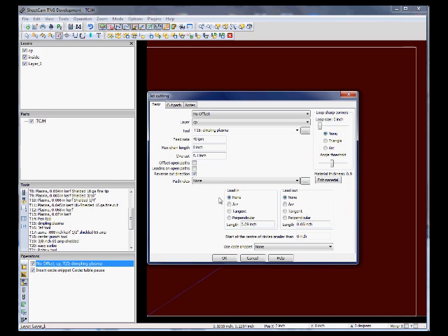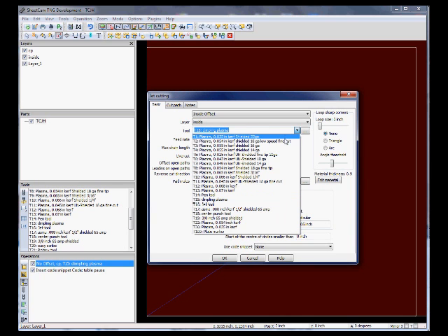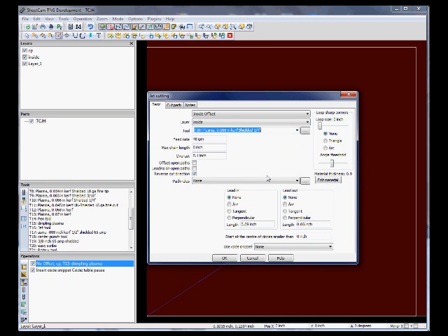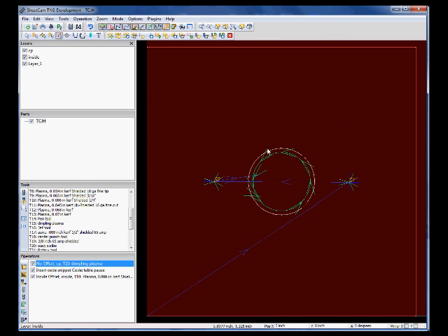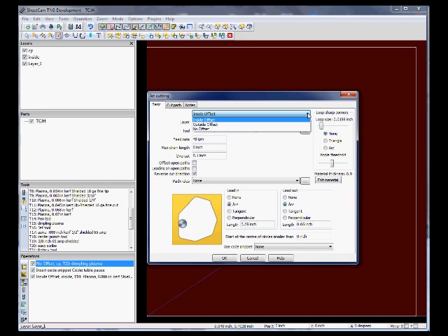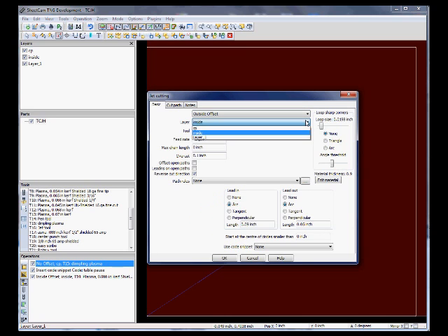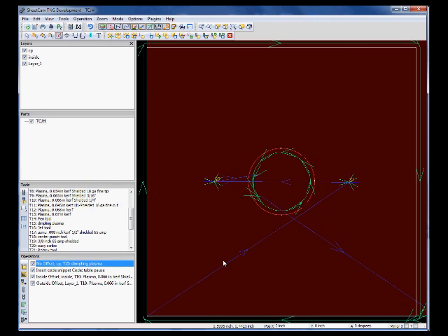and then the next thing I come in here, I'll do the inside offset, and I'll say do the inside and change it to whatever tool you're going to use. Let's say I'm going to use a 1/4 inch. So all the settings are there. You can have lead in if you want, and lead out if you want. So you go ahead and click that, and you see it is set up here to cut the inside, and then the other part is the outside, which is going to be outside offset, and it's going to be layer 1, and again inside, arc in and out, lead in and out, or whatever. So there's your finished thing, and you would go ahead and then do your post-processing.